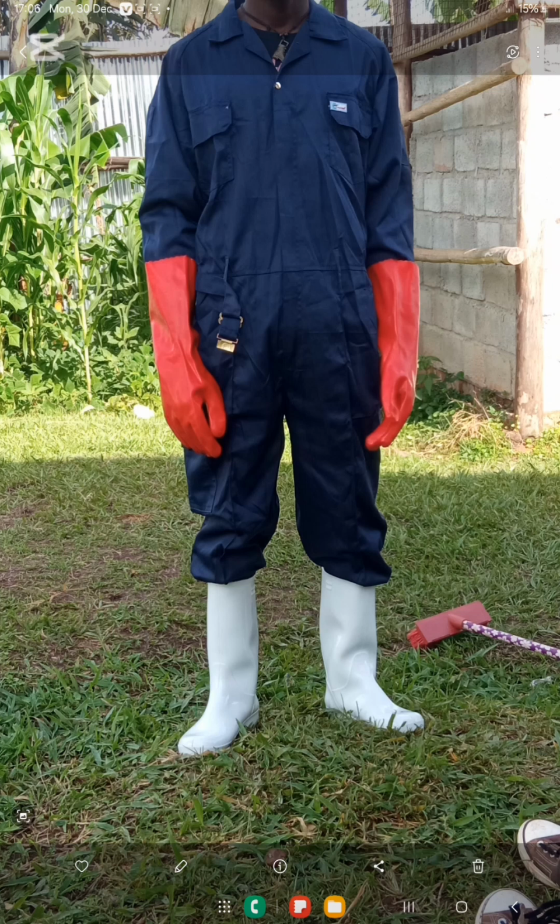And then for the caustic, I talked about it. When you pour caustic, you first pour water, and make sure you have a mask on. Then you stir the caustic with a long stick, and make sure caustic soda or caustic solution does not touch your hands or any part of your body. It will itch, or even cause wounds. It can injure depending on the concentration and the quantity that has touched you. So it is important. Always have separate buckets or equipment that you use for caustic and for the others. Separate them, segment them and document them. So let's go to the next one.